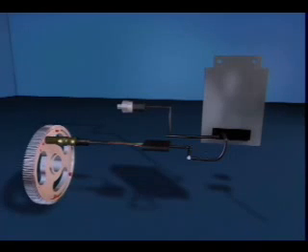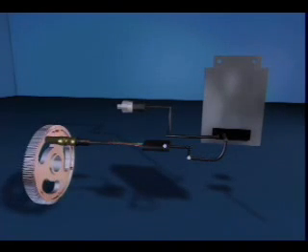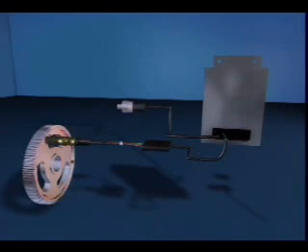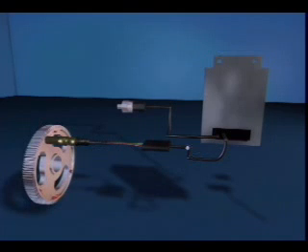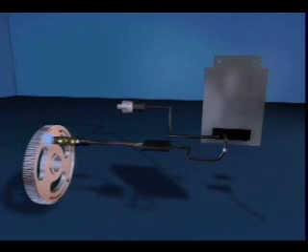The engine position sensor is mounted in the gear cover. The engine position sensor measures the position of the engine camshaft by the use of a variable reluctance sensor and 7 cast protrusions located on the rear of the camshaft gear. Whenever the cam gear protrusions pass the engine position sensor, the deflection in the sensor flux line generates an alternating current signal to the ECM.